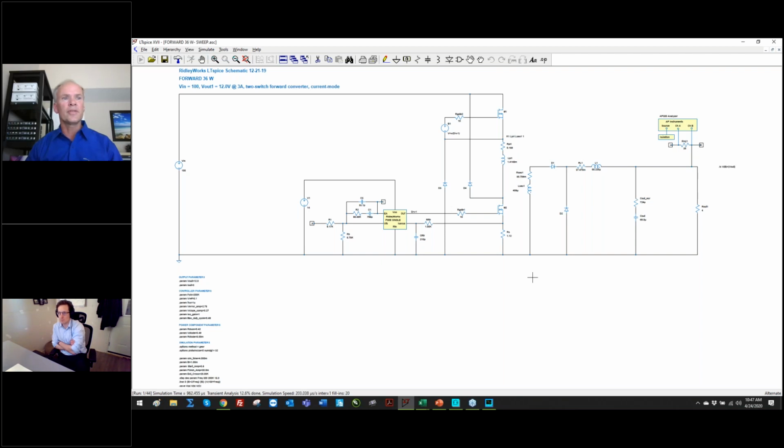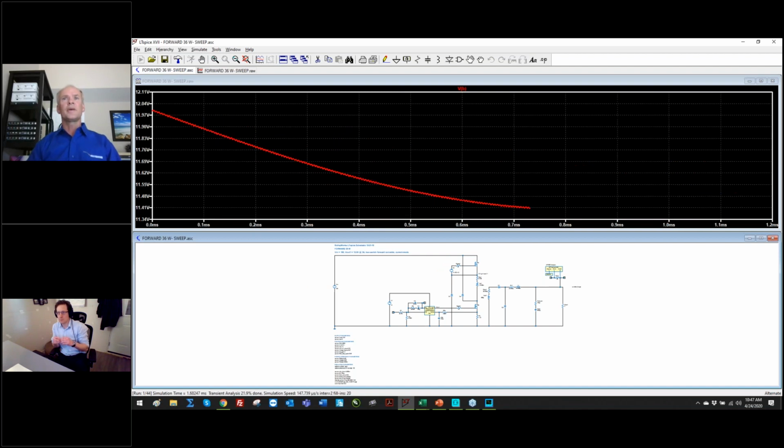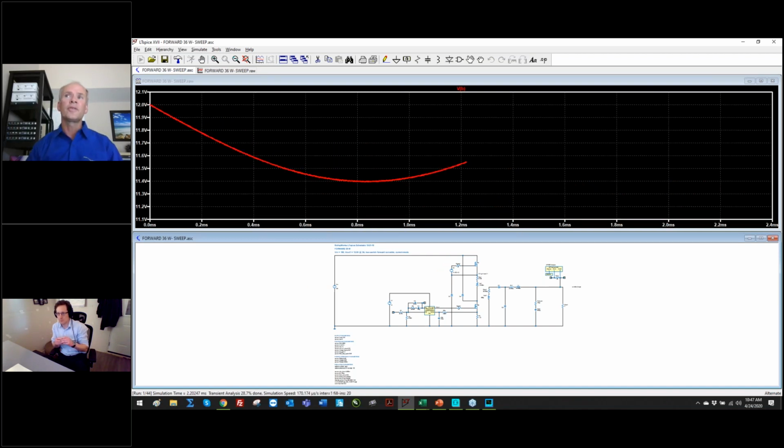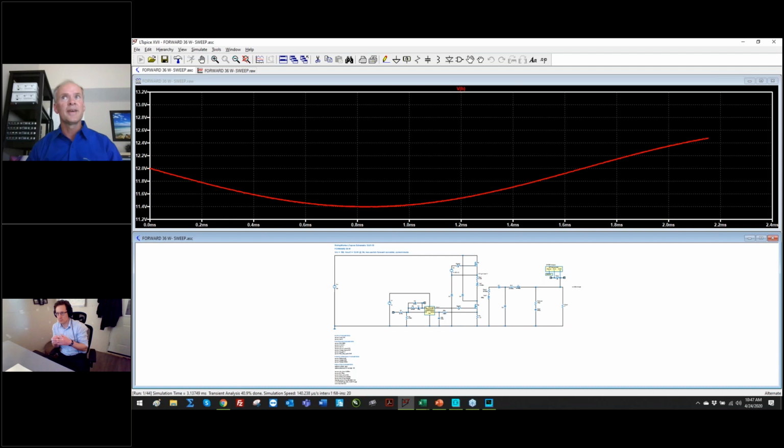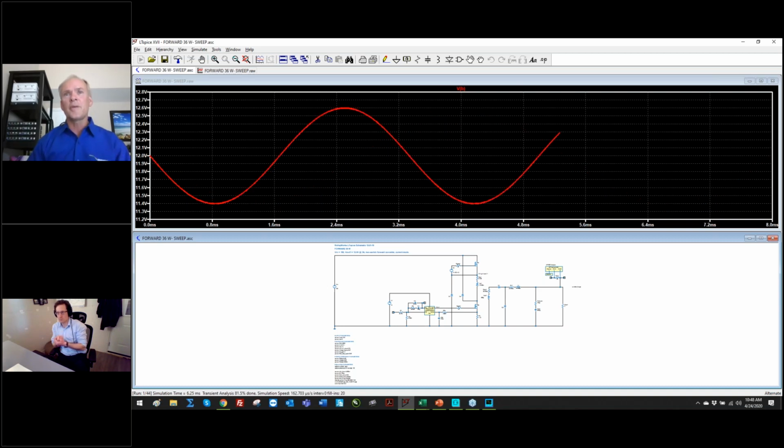It has to go through an initial startup transient to find its steady state. And then here we are. We're actually sweeping a 300 hertz sine wave on a 200 kilohertz converter. It's a little bit slow because it's LT Spice. It's got a lot of work to do. Sweeping through, we need at least 2 complete cycles of sine wave here. But to be fair to LT Spice, this was not possible 5 years ago. You would have waited so long for this to come out that you just couldn't do this kind of approach. Mike Engelhardt did a fantastic job of speeding up LT Spice and optimizing things, using the multi-cores, whatever they do. That's not my domain.